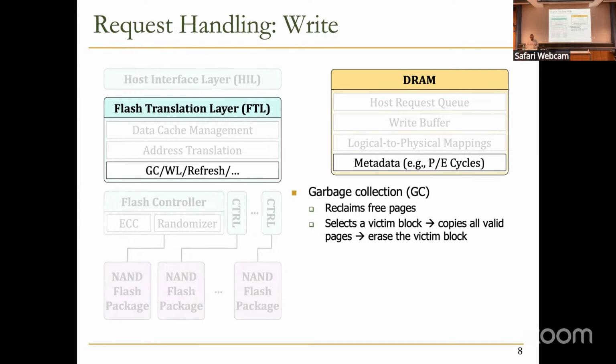But essentially, garbage collection is to reclaim free pages. So in garbage collection, we find a victim block, and then move valid pages from that block to some other places, and then erase that block to make enough free pages, essentially. We're going to see more later, but that's the procedure of garbage collection, which can be invoked after several writes.